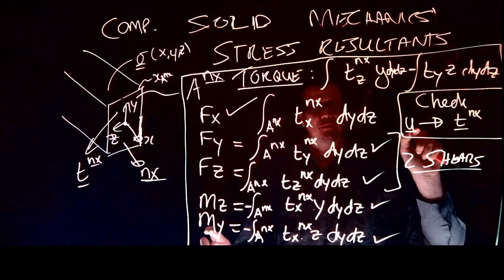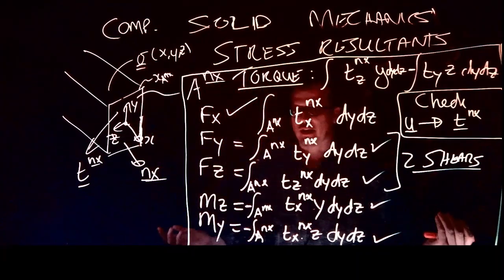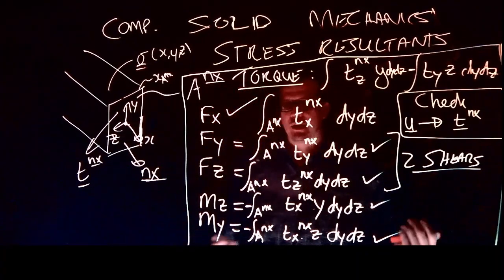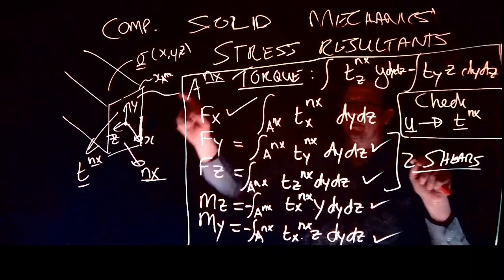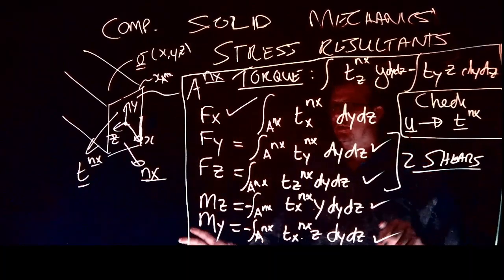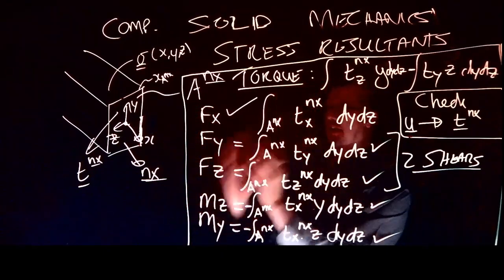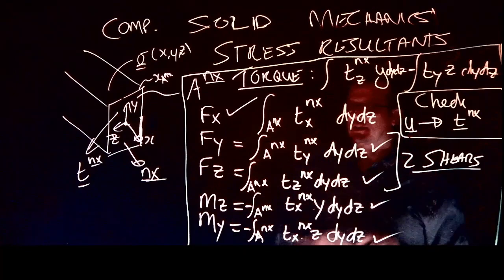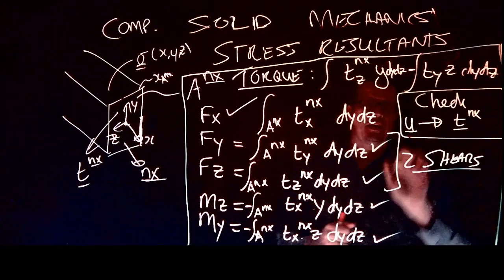If I give you the displacement field, I can't give you the tractions independently. It's already incorporated. All I can do is check whether the tractions I derive on those surfaces, and the macroscopic forces like shear and normal forces, bending moments and torques, are consistent with what is claimed to have been applied in the problem.